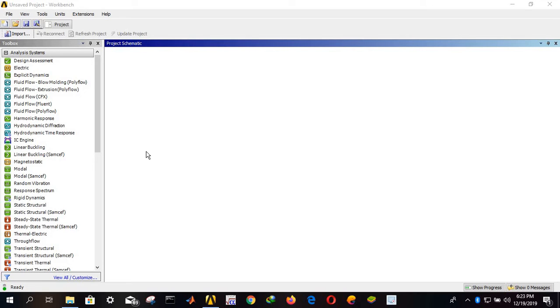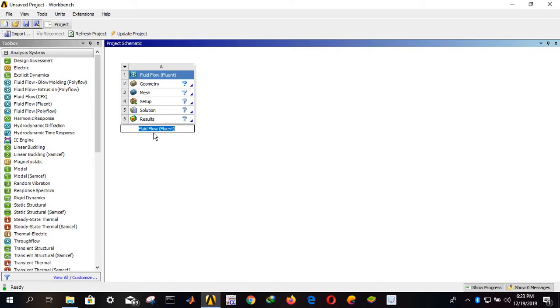Hey everyone. So in this video I will show you how to get a temperature distribution in a 2D plate. For that, first of all you need to open Ansys Workbench and you will see this kind of white window here. In that you have to double click on this Fluent. Here you can give any name that you want for your project. I am keeping it as it is.